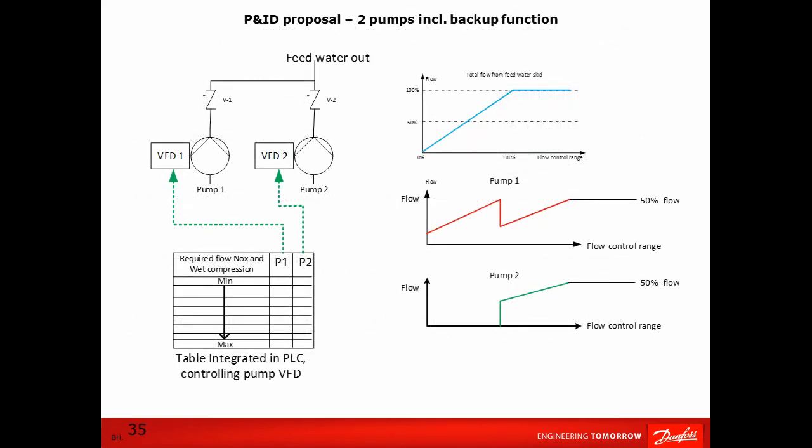Here, you can see an example of a two-pump system redesigned with VFDs on both pumps. VFD ensures that the two feed pumps never run at maximum flow. They share the load and both operate at reduced flow conditions. This will reduce the shaft speed and eliminate the risk of cavitation. Another benefit of VFD is energy savings. VFD allows the pump system to deliver the required feed pressure and only that at all times. What happens if one of the pumps fails? The next slide will explain.